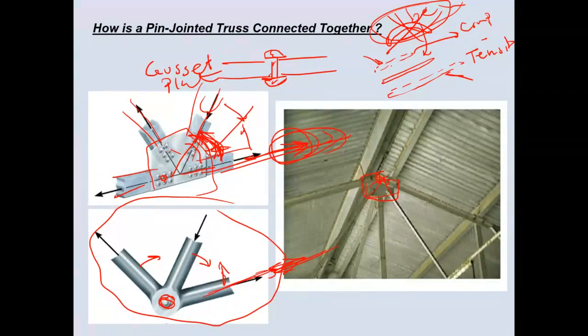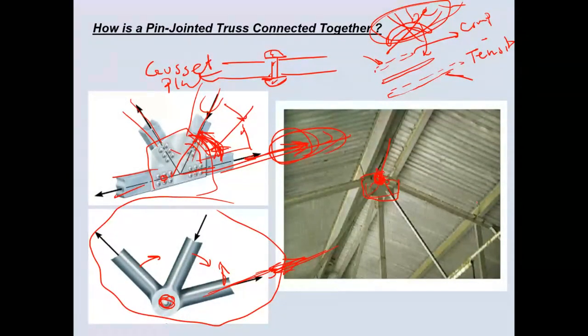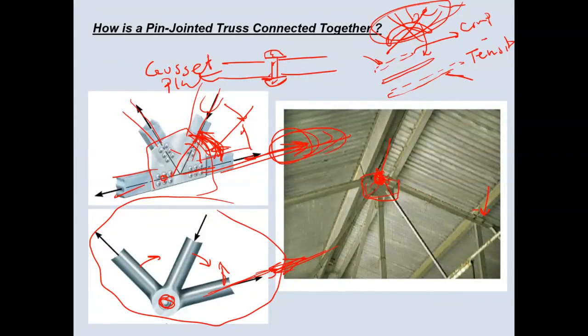Why doesn't bending happen? Because all forces can only act at the pin. So there is a force here, there is a force here, but no force between these two. If that ceiling is resting against this bar, it would bend it. So with the truss structure, you can only apply the load at the hinges. You cannot apply it between two hinges. Let me explain to you further.